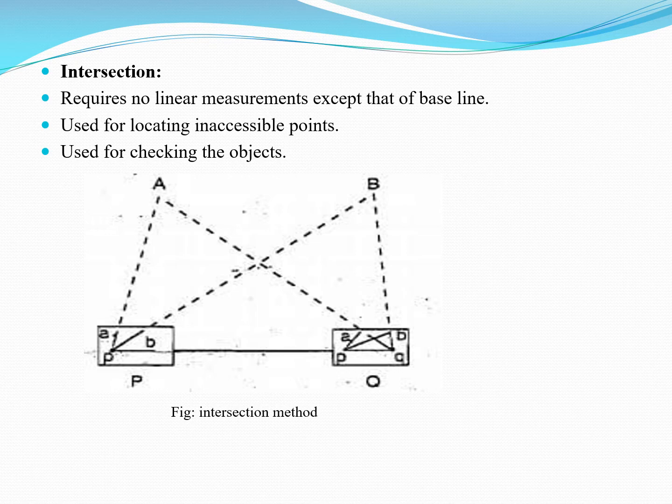By using the trough compass, the north line is also marked at the right top corner of the sheet. After that, the alidade touching point P, objects A and B and the ranging rod at Q are bisected, and the rays are drawn along the alidade.